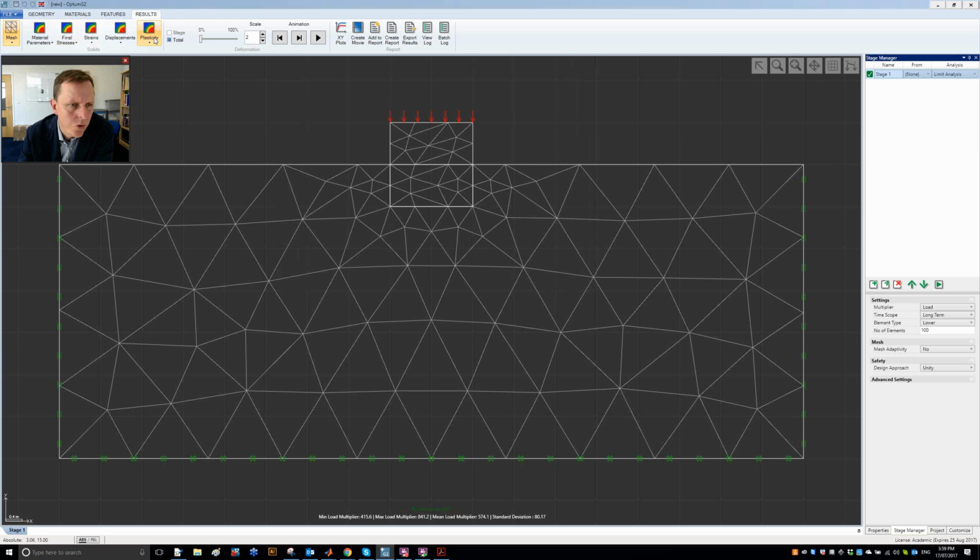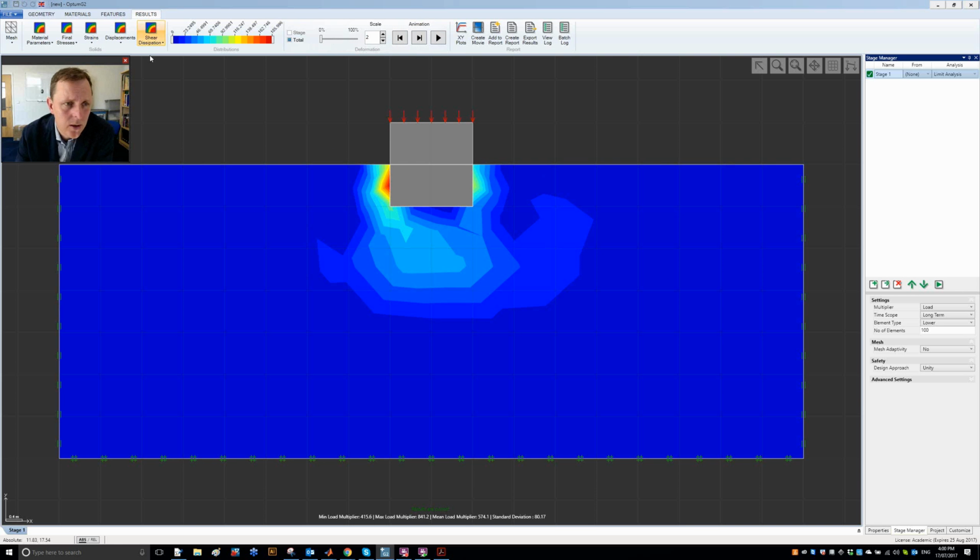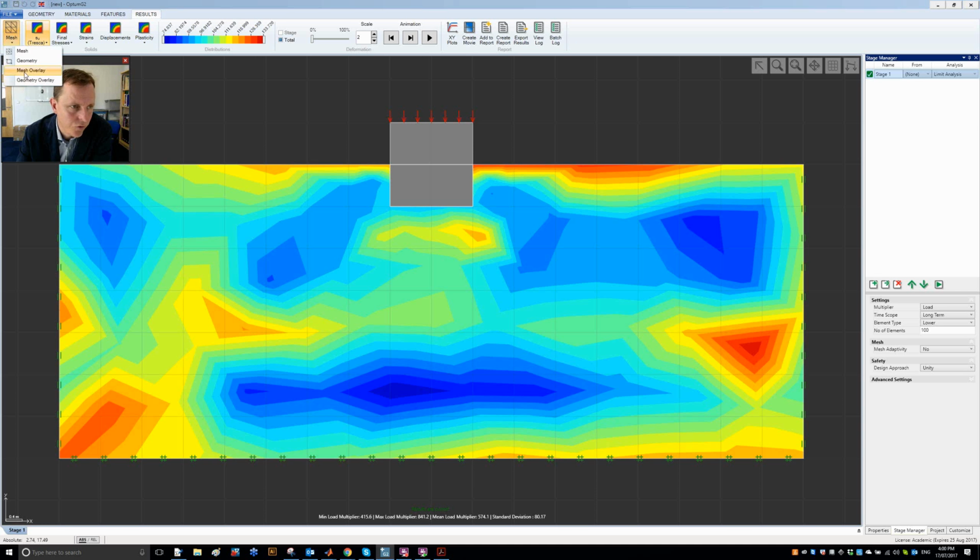The results shown here are not going to look very nice because it's just for 100 elements, and the results are referred to the results of the last run. So just be aware of that. Since it's such a coarse mesh, it's not really going to look very good. If you want to recover the results of a particular realization of a particular Monte Carlo run, you can do that by setting this seed, but that's all described in the manual. I won't go into details about it here, but you can recover the results of all runs if you really want to.